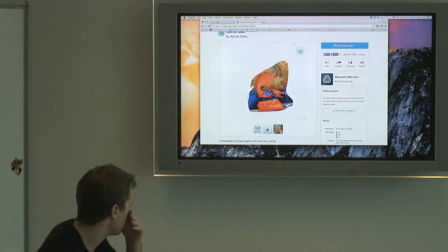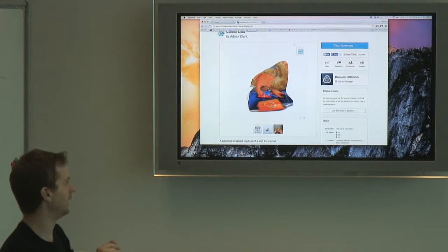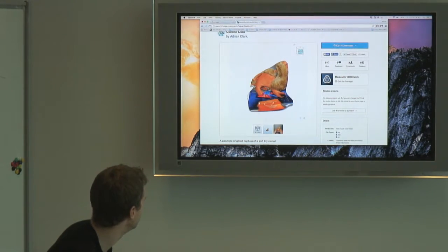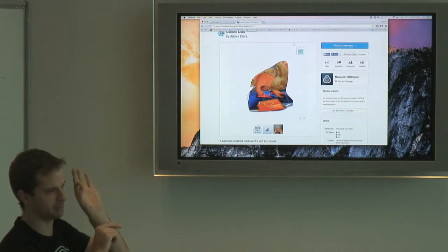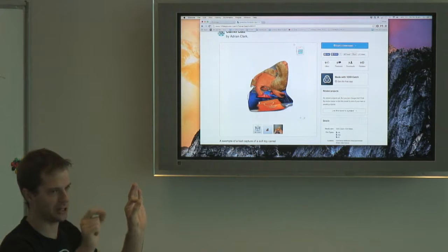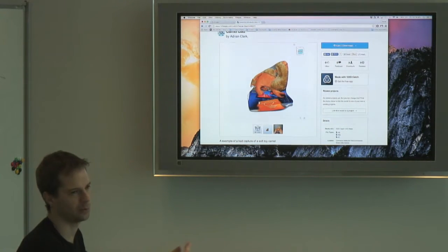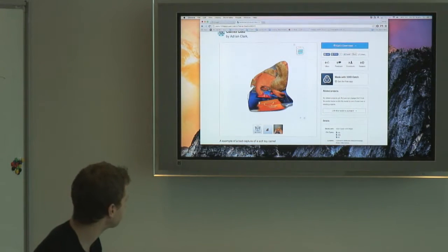And what happened in this one when it failed is basically a whole bunch of the images it was not able to find these correspondences for. So what you can actually do is you can go in and manually say, okay, this point, you'd pick maybe a corner point or something. So you might say, the very corner of this orange square is here in this image, here in that image, here in that image, here in that image. You basically say where these points are, and with a minimum of 4 points in each image, it can figure out where the camera was in each frame.